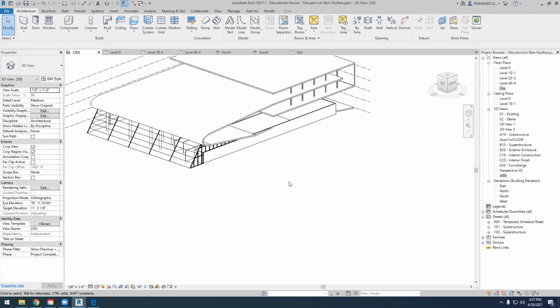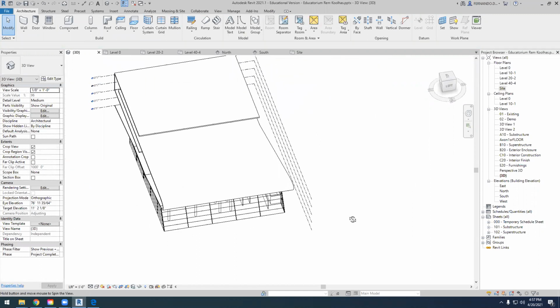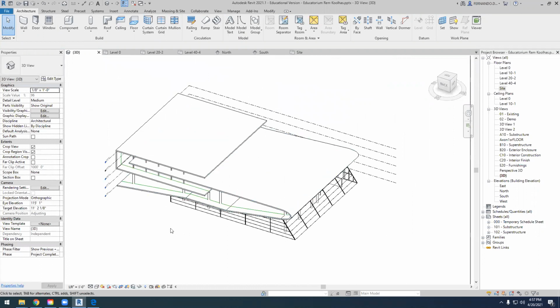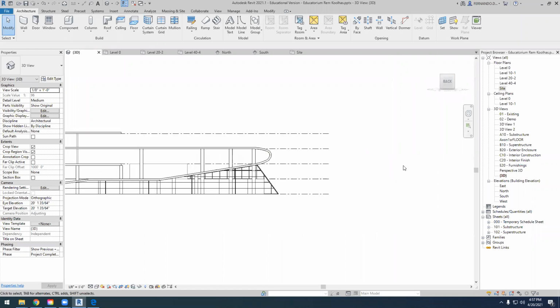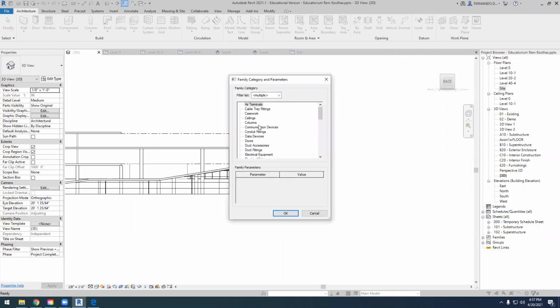it's good knowing different options, because sometimes something is not working for some reason. So you have to be resourceful, and you say, okay, if I can't do this by extrusion, I will do it by footprint. If I cannot do it with a roof, I will do it with a massing inside. And there's still another option. So just splitting hairs, we have another option that can be the architecture component model in place. If I'm generating a model in place, I can decide what kind of element I'm designing. So I can design a roof.